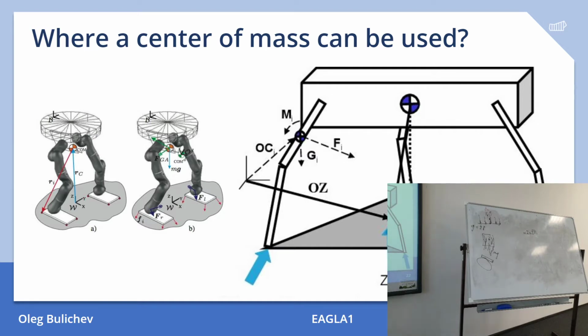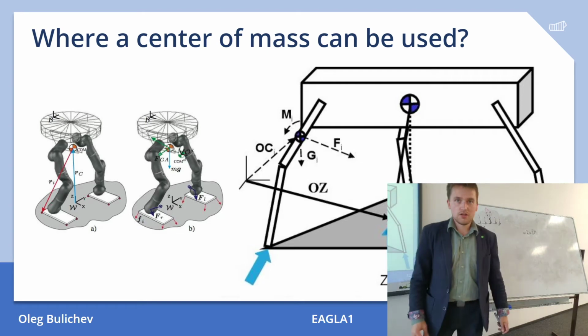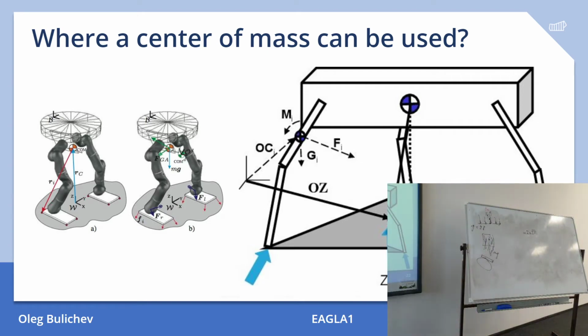If you remember the Boston Dynamics robots, they can fall. Why? Because when they move, if we just turn off the motors, the robot will just fall, because its center of gravity does not work like this. So in a bipedal robot, you assume that your foot is not a point, but a rectangle, for instance. And your polygon will be based on these 1, 2, 3, 4 points. And your center of mass should be in the center.